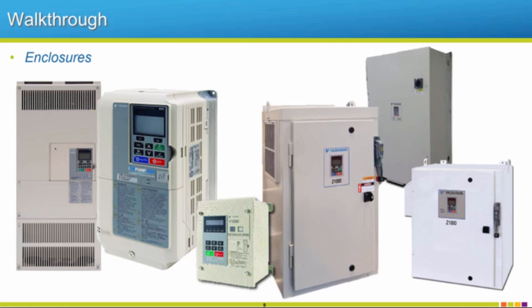Their uses could be anywhere from indoor use with a light degree of protection, so maybe there's just a little bit of dust but a fairly clean room that the drive is located in, all the way to outdoor use on top of a rooftop in the middle of summer in Texas or a winter in Chicago. So there are varying degrees of enclosures depending on what kind of environment you're going to locate them in. Some of these even have hose down capabilities, so you can spray them down with a hose, like the NEMA 4X.